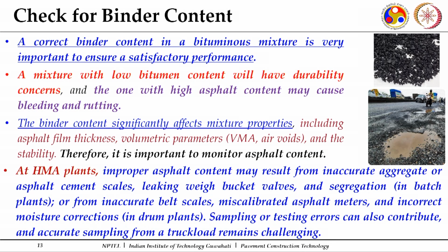Now, after the aggregate gradation, another important parameter is your binder content, which plays a very important role in the performance of a bituminous mix. If there is a mix with a lower binder content, then it may have some durability concerns, because binder is required for giving resistance towards moisture induced damage, and the desired resistance towards cracking and fatigue.